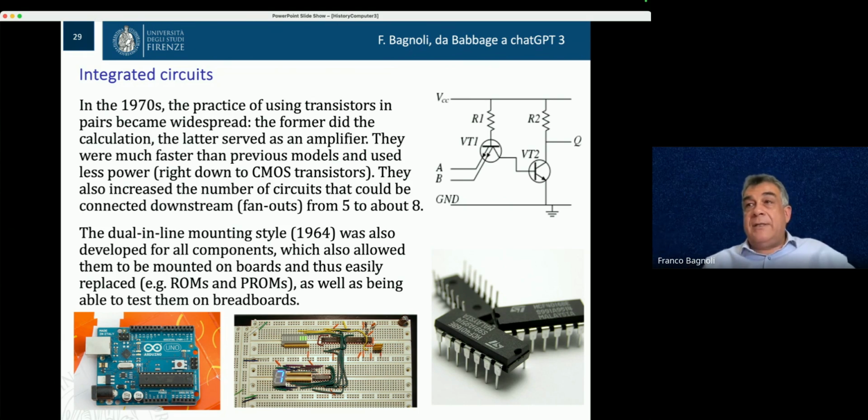So you have to be sure that the output power of your chip is enough to furnish the current to all of the following circuits. If you have a dedicated transistor to provide this current, you can have enough fan out so that you are less worried on how to design your circuit.